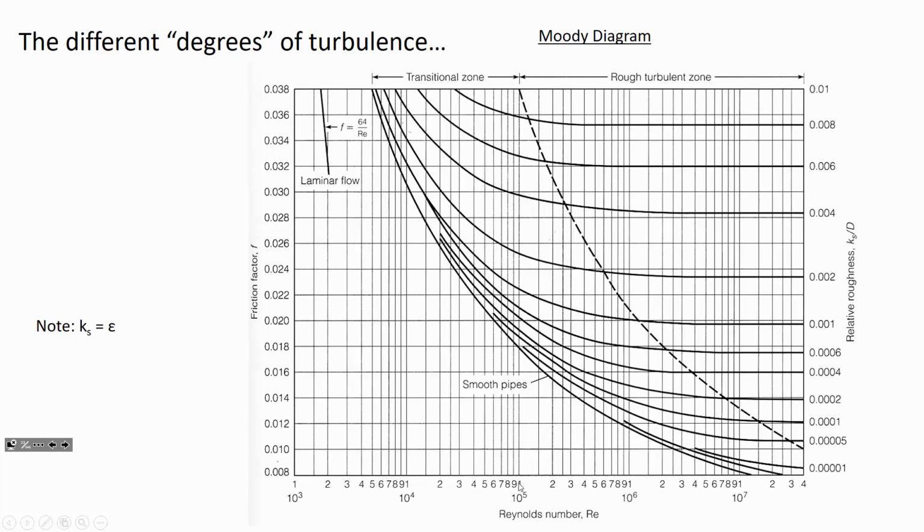So it's a logarithmic scale. Here's 1 times 10 to the 5th. Here's 2 times 10 to the 5th. This one right here is 1.5. So we're going to be between 1 and 1.5. So here's 1.25. I'm going up until I intercept this curve right here. It miraculously happens to be a value where we can go over to the left really easily and find that the F value is 0.022.